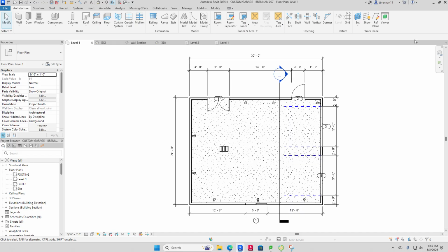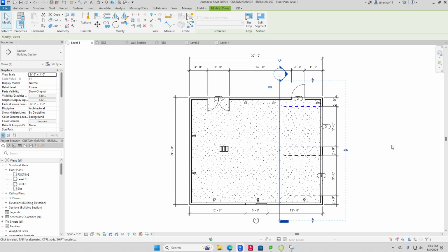You select one of them. Click on the line and just go ahead and delete it. So get rid of one of them. And we're going to adjust the actual section boundary for the other one. So this is how you do that. Click on this line right here. Click on that line, and you'll see the section boundary out here. It's a light blue line. You guys see that light blue dashed line? Okay. So you want to grab the control.